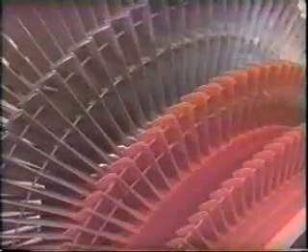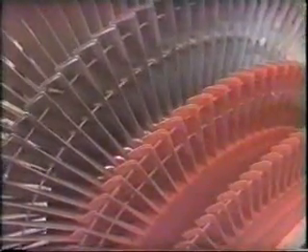You may well ask, but why can we not operate at a lower frequency, say 58 hertz? Well, the first answer is that certain customer equipment may not function correctly at low frequency. Also, most modern steam turbines cannot operate at low frequency without damaging some of the turbine blades due to vibration.